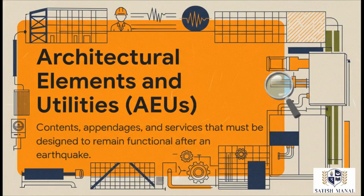Here's another massive change, and this one directly expands our scope of work. It's the introduction of AEUs, that's architectural elements and utilities. For the very first time, the code is explicitly holding us, the structural engineers, responsible for the seismic performance of non-structural components. We're talking about designing connections and supports for everything from cladding and partitions to critical piping and HVAC systems. Our job isn't just about preventing a structural collapse anymore. It's about making sure the building is still functional and safe for life after an earthquake.